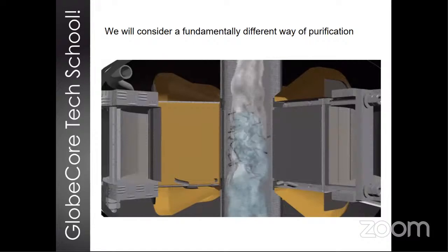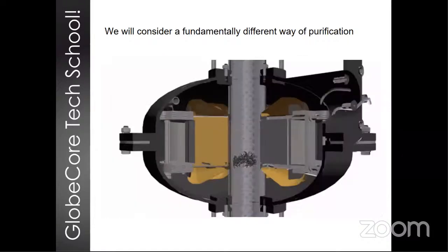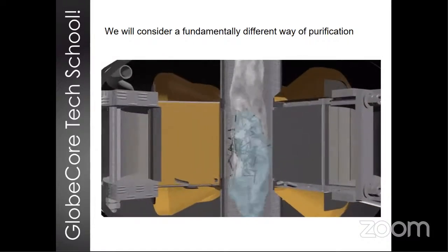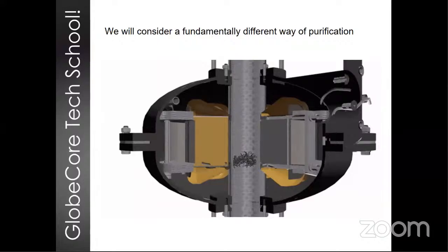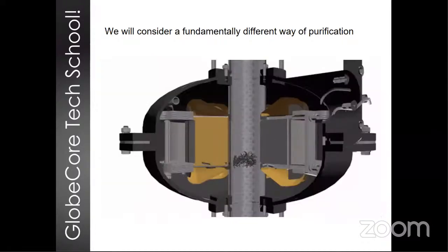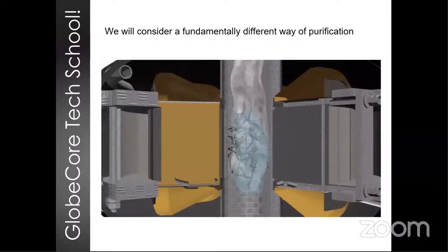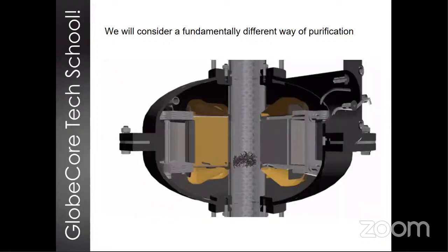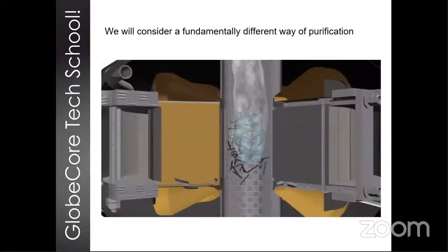So if water passes through this area, through this environment, along with impurities, then we have the combined effect of high power shock waves, cavitation, which is a discharge of energy in water, and the resulting ultrasonic waves that all have a combined synergetic effect on the water and help promote the physical and chemical processes that allow us to remove the impurities from the water. Let's go to the next slide, please.